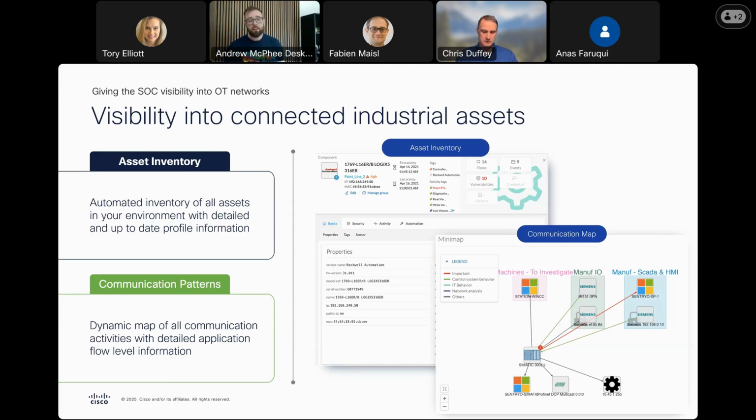And what we get is a detailed profile of what devices are. So for example, in this case, it's very small, so sorry about that, but there is a device that is a Rockwell Automation controller, and you can see in red, stop CPU. We're able to see the Ethernet IP command that someone tried to stop the CPU, or we see resets, we see reads and writes and program downloads, the details of what's actually happening in between them.